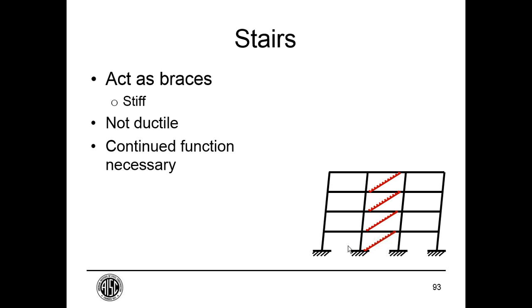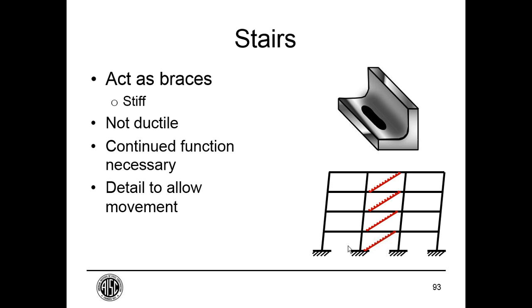So we really want to protect the stairs by removing them from the load path. We need to detail to allow some movement, and not only allow movement, but maintain gravity support even at that movement.